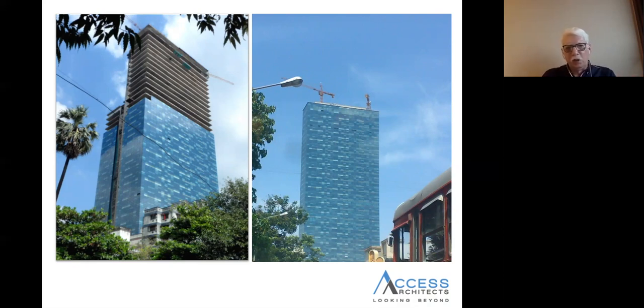So one major thing which all of you need to know is most of the time the glass facade is actually hung. They are not fastened to both the slabs. So in this building it was 4125 millimeter slab to slab. What we had done was a bracket which was selected, which would allow the facade to move in 3 dimensions. So all the 3 axes it moves. The intent was that whatever building moves because of wind, seismic, or settlement of the building of this height, some part of this building, the glass facade, would remain at the same position. So there is no leakage, which is one of the major and critical criteria, particularly here in Mumbai.